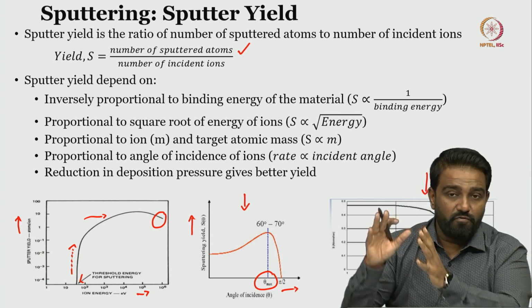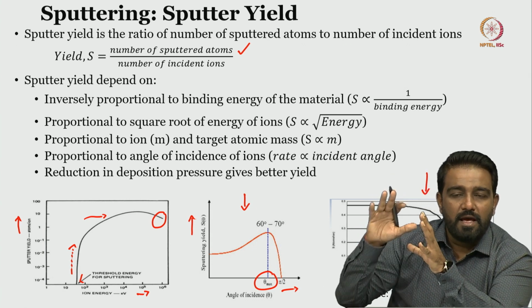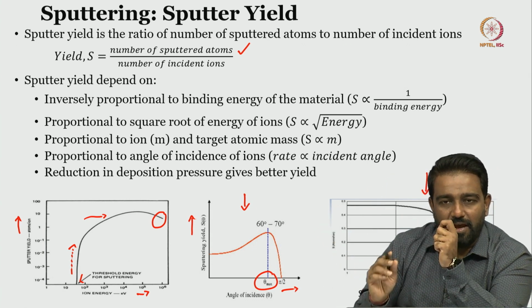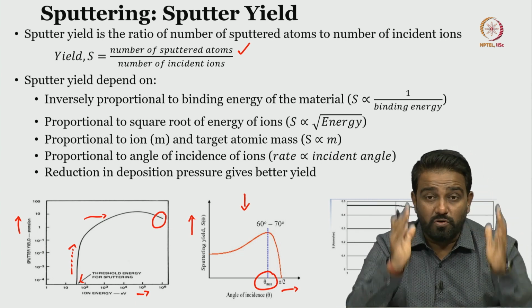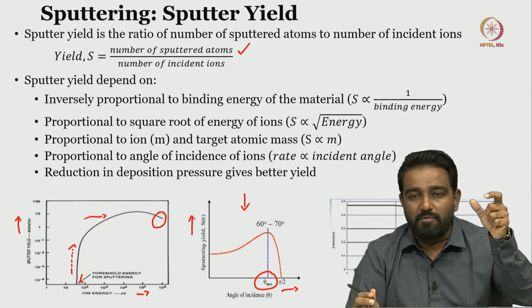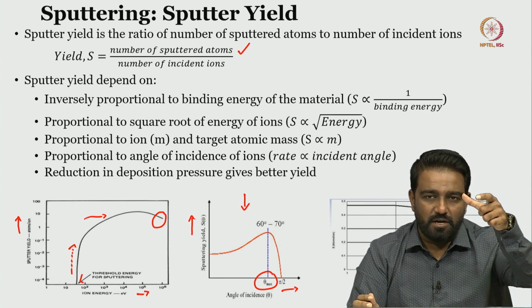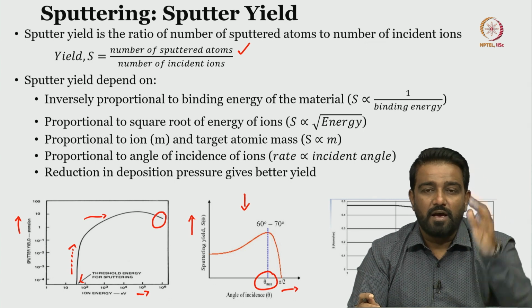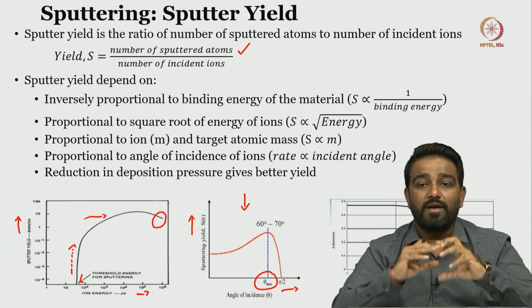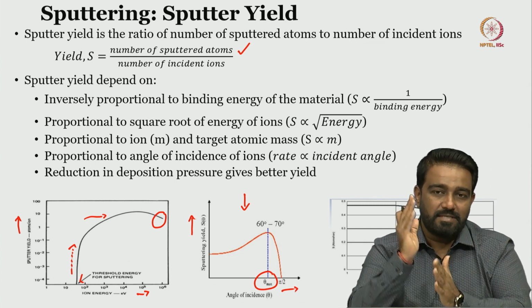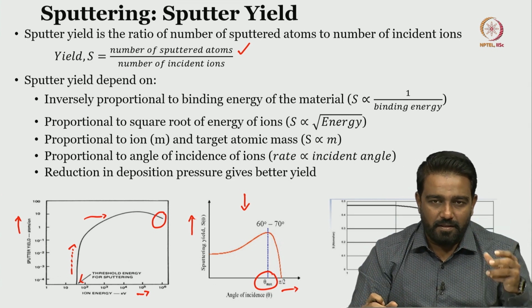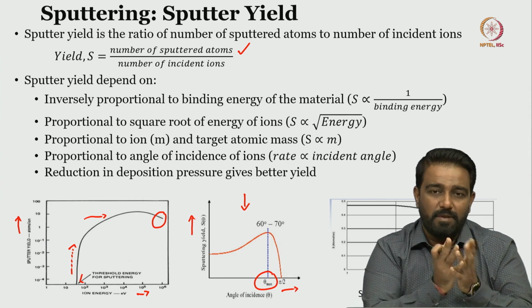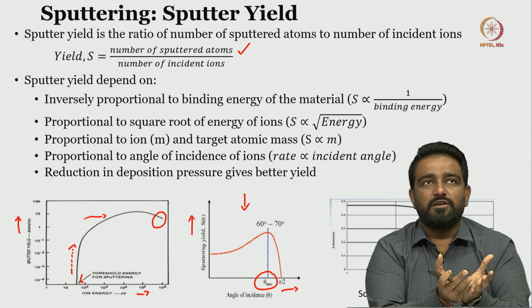So, we also have corresponding lab videos, where we have recorded how the e-beam operation works, how the chamber looks, where the QCM, quartz crystal monitor, is, where the substrate holder is, how the source looks, how you can close the chamber, how the vacuum is created with the primary pump and secondary pump, and how the pressures are measured. There are 2 pressure gauges: one is a Pirani gauge for pressure close to 10 to the power minus 3 torr,